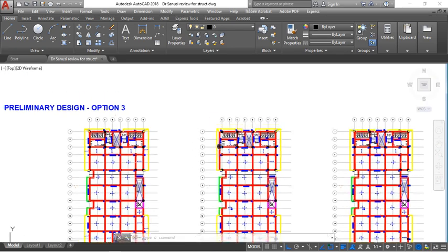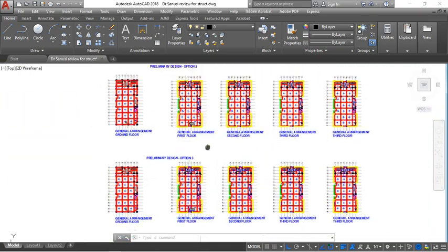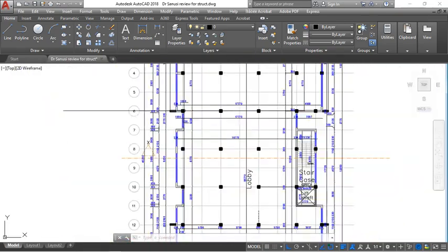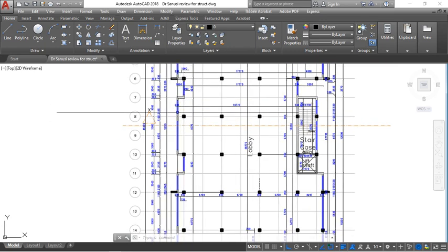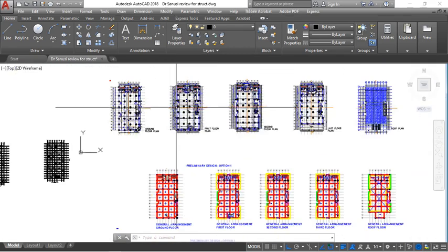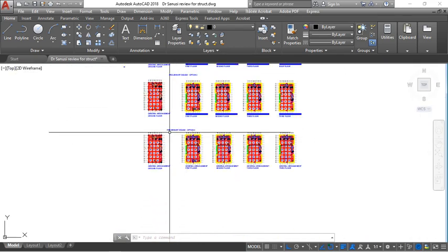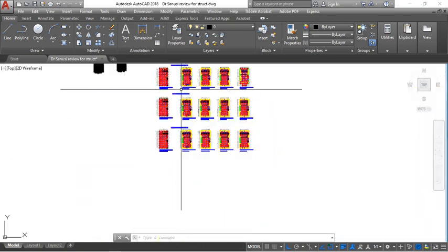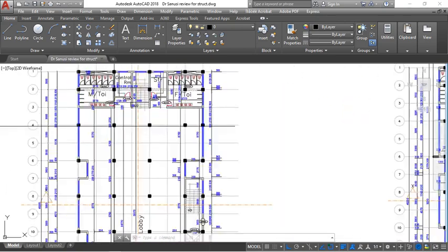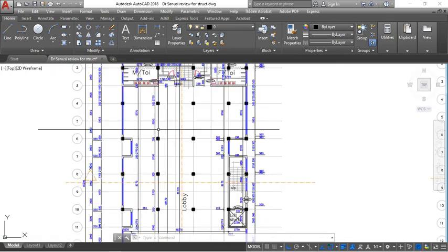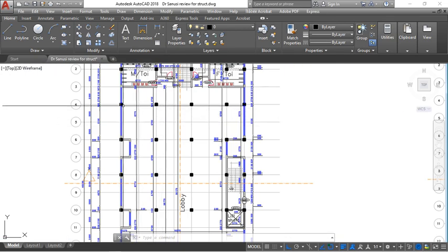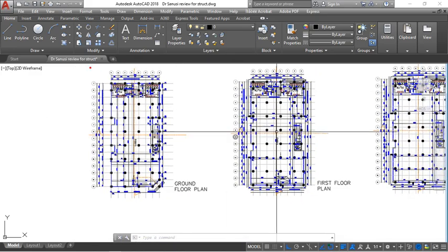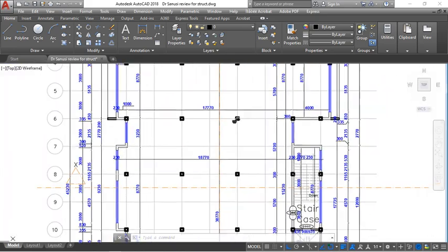beams at the edge. These beams at the edge will cover this area of the design. Generally, I didn't go further with option 3 because the design is for an event hall, so there won't be an issue if these beams are visible after construction.